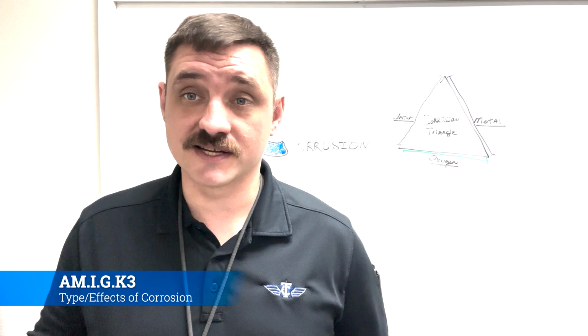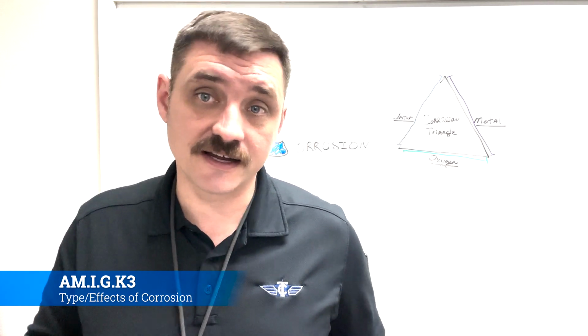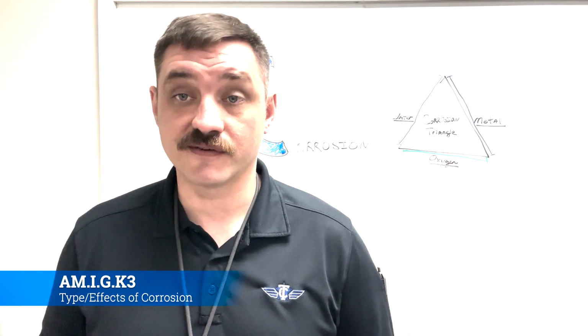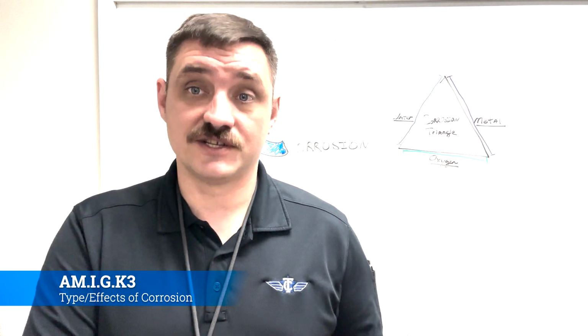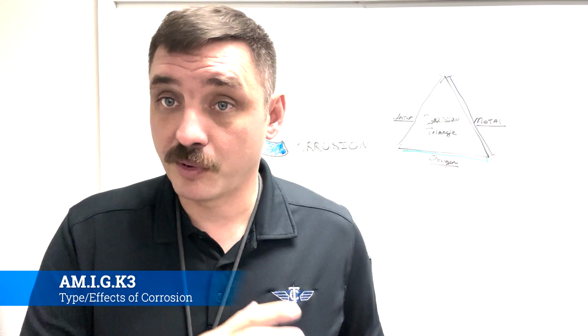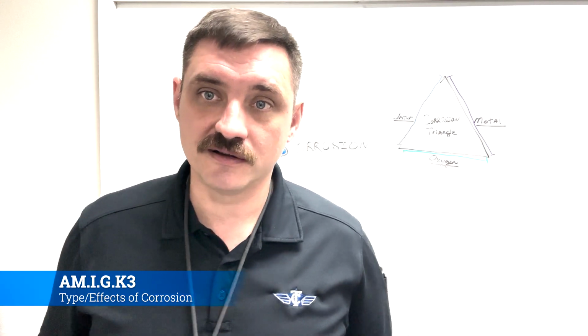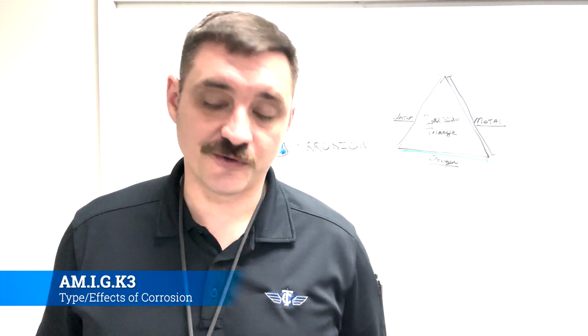And corrosion is a process that produces a product at the end of it. Like on iron, it's oxidation. On aluminum, it's that white chalky substance. But whatever is happening there, it's starting to create more or less a big boil or a cyst or a pimple, and it boils up, and then you can lance it and all that white stuff's up in there. But that's exfoliation corrosion.